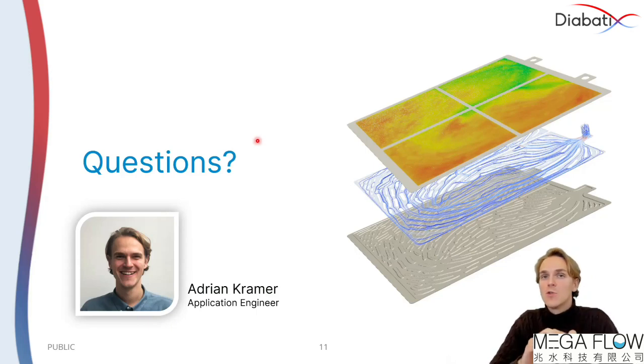Whether it's a cooling sleeve that's cylindrical, that can absolutely be the case. If your design regions are cylindrical or of any other shape other than the rectangle that I just showed you, that's absolutely not a problem. There are no limitations on the input geometry or the design space itself where the optimizer is allowed to place the channels. So no worries there.